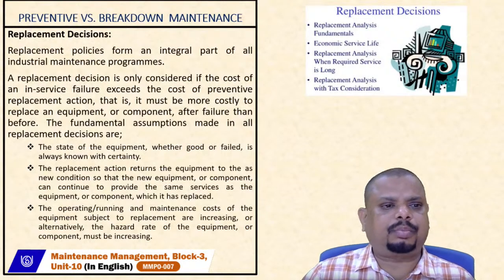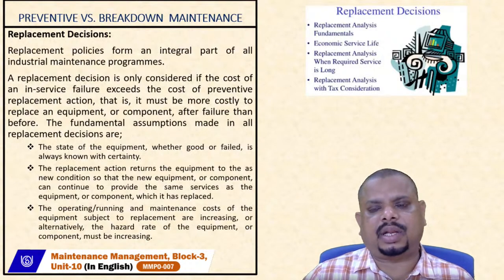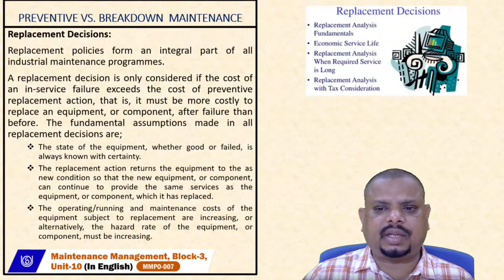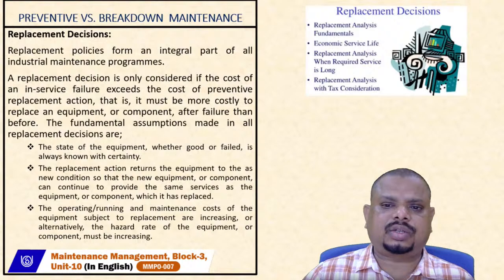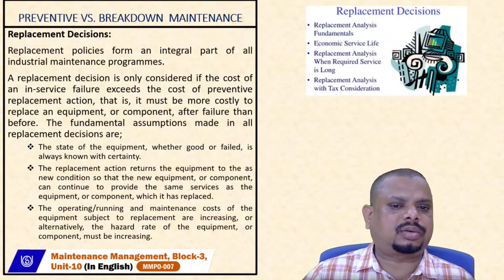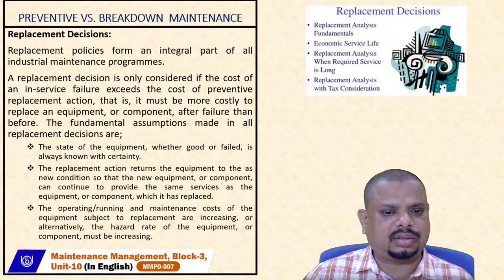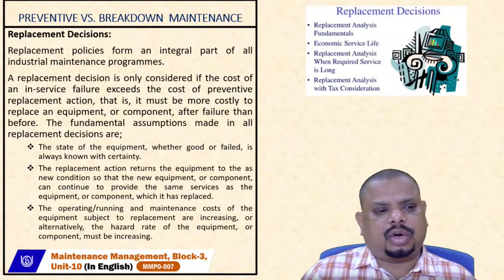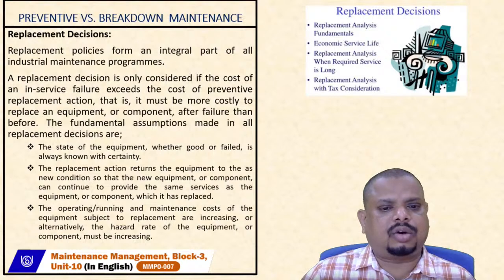The replacement policy forms an integral part of all industrial maintenance programs. But whenever you think about replacement policies, the cost consideration should be in your mind. The cost of preventive replacement actions must be less than the cost of replacing equipment and components after failure than before.